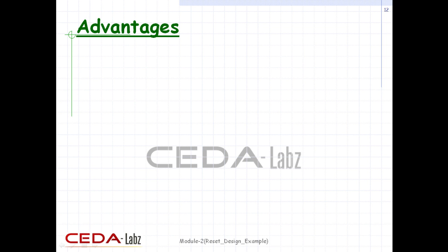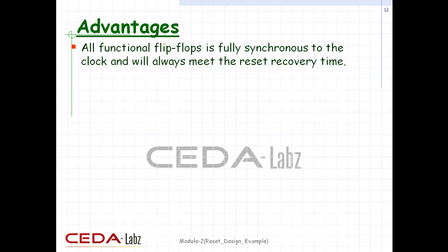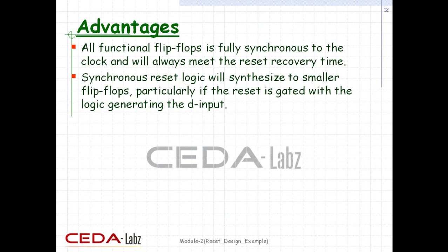The advantage of this type of topology is that the reset presented to all functional flip-flops is fully synchronous to the clock and will always meet the reset recovery time. Synchronous reset logic will synthesize to smaller flip-flops, particularly if the reset is gated with the logic generating the D input. But in such a case, the combinational logic gate count grows, so the overall gate count savings may not be that significant.